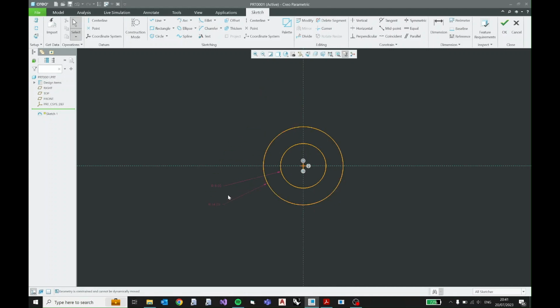All the dimensions in this video that are purple are locked. We can still change it by double clicking it and then changing it over here. For example, say 9. But again, since this is purple, this dimension is locked, so you cannot dynamically change it. So I'm gonna make it back to 8.0.